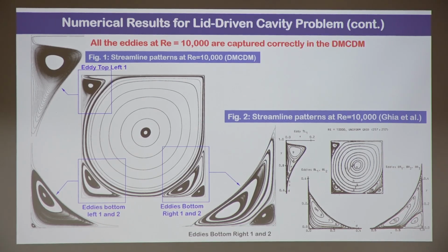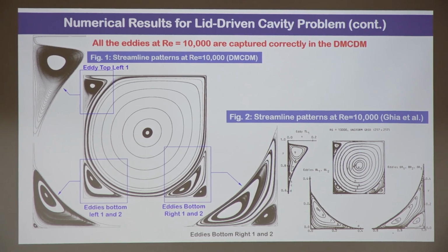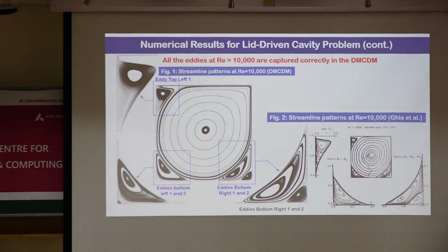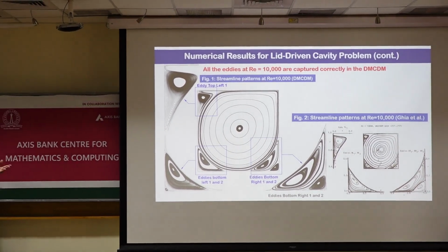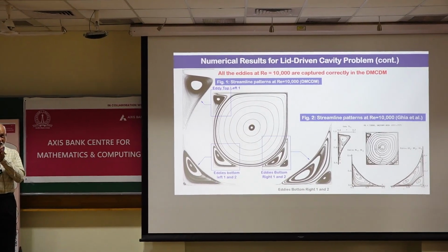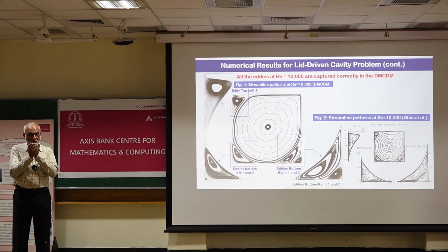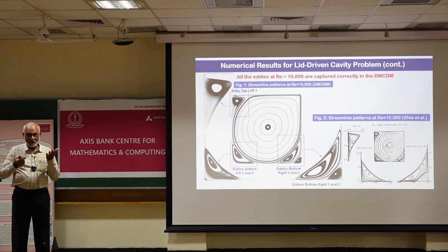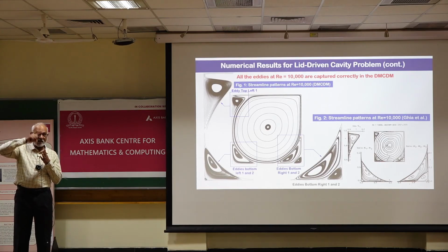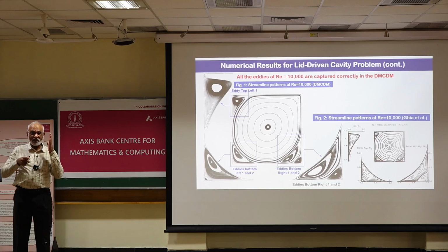And suppose you make this cavity a very narrow rectangular channel. What happens? Then it will break. Along the height of the channel, there would be many recirculation zones. And that's exactly what happens in the countries where cold and hot are equally there. They have double glazed windows with a small gap, a very infinitesimal gap, because that is how you protect loss of energy. So the fluid, which is air in this case, inside will recirculate there and create a boundary layer to insulate.